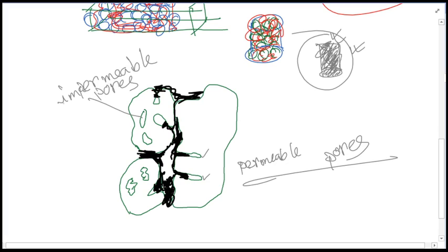These pores are within the individual aggregate. But when all the aggregates are combined in a manner, as you can see here, the combined aggregate will create some voids. The void where the bitumen has been filled, this filled bitumen here, as you can see, these will be called the air voids.